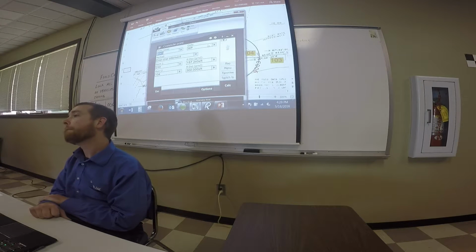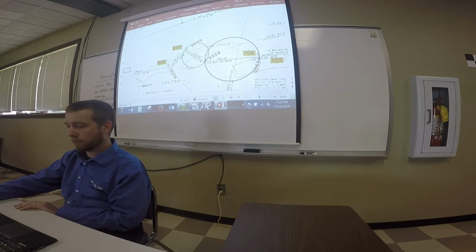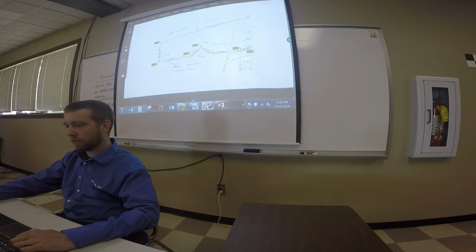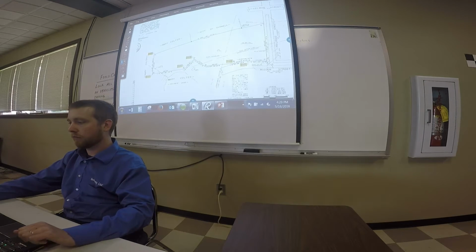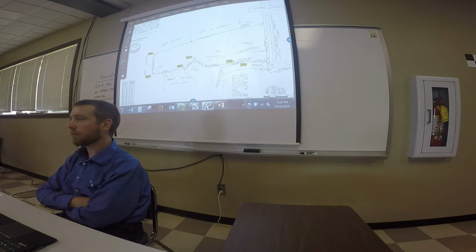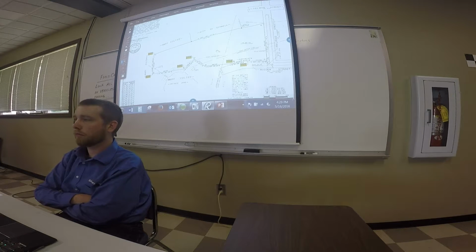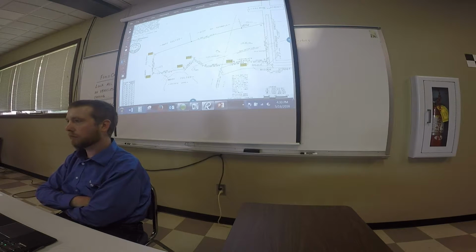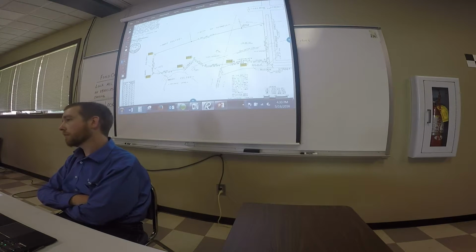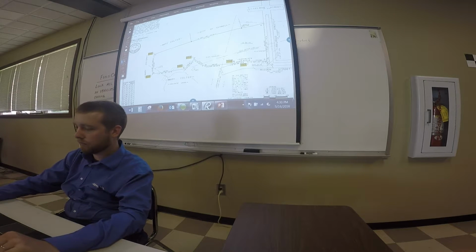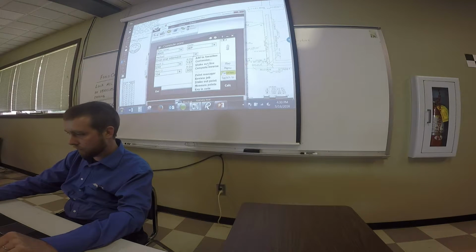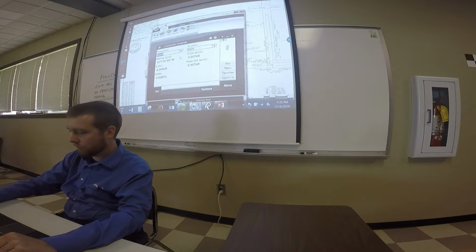Yeah, sir? So, never, minimize that screen there, go back to the plat for a minute. So never embark on doing a distance unless you have confirmed that your field data closely matches the plat between the two pins you have found. If that makes sense. So what I would do very first is I would inverse between 210 and 104, and I'd write that down. Then I'd inverse between, who's going to do that right quick?